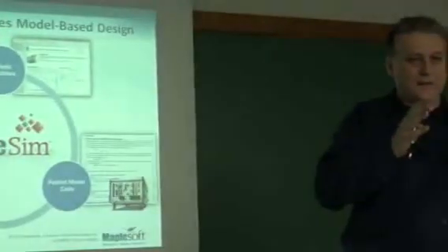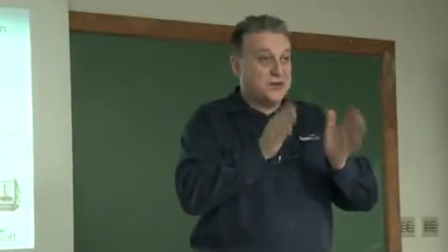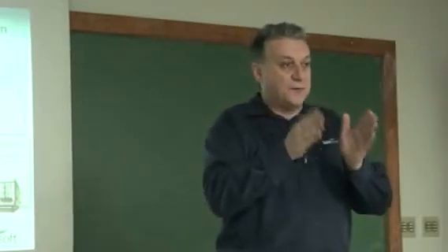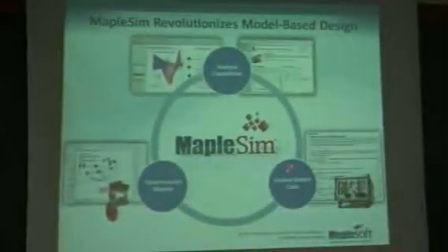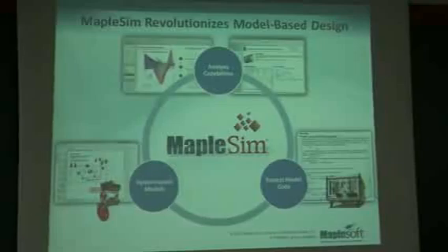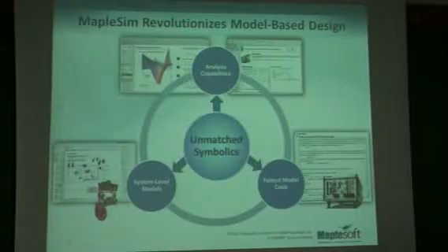The other application is if you want to take this system and run it in a real-time environment. You have a very narrow time budget in which to execute your code for your plant model or for your system model in a hardware-in-the-loop or real-time system. So it's critically important that you can get code that is as fast as possible and maintain the fidelity of the model that you're representing on this real-time system. And we can do this because we have this powerful symbolic capability. So everything comes down to the ability to generate equations for doing this.